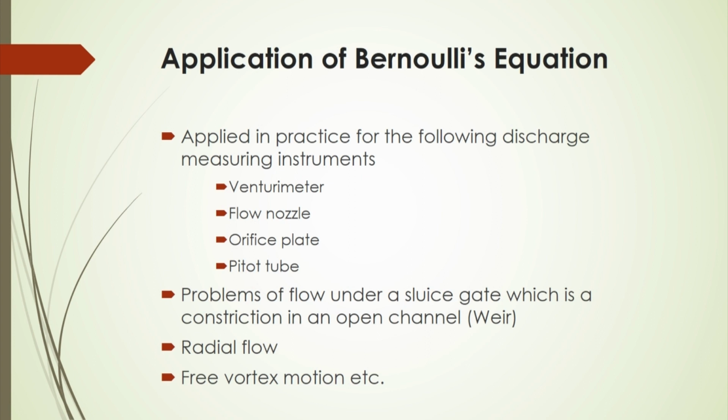And we have already shown earlier the sluice gate operation, the design of that gate and how much pressure is produced there. Once the velocity through the river is known to you, then the pressure developed can be calculated based on these energy equations. Also, if you know the pressure head in the flow, then you can find the velocity. And through the weir also, you can calculate the flow rate, based on this conservation of energy law.